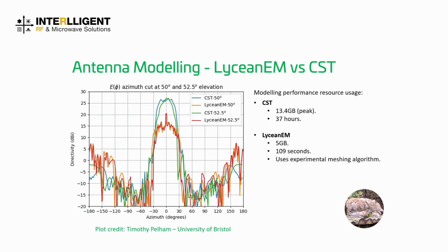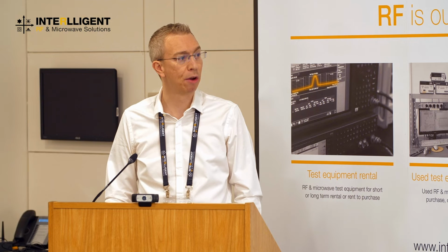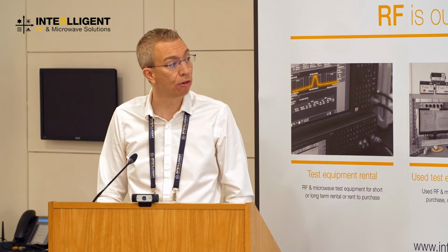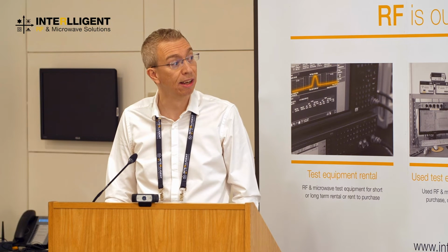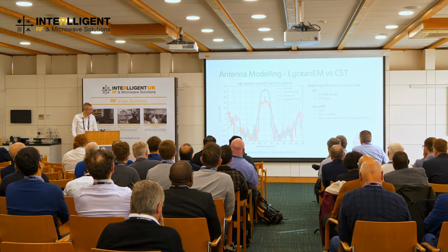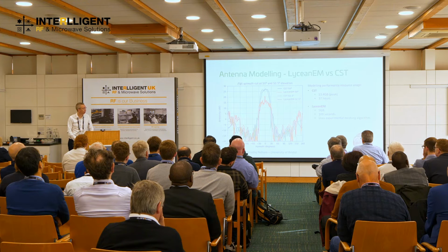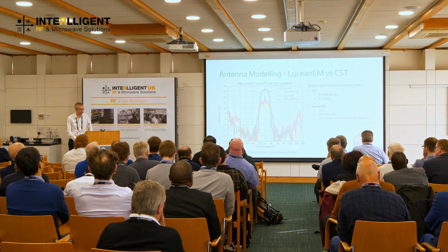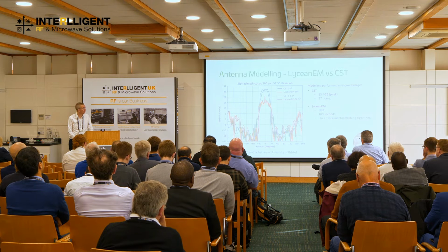Timothy Pelham at the University of Bristol did some modelling for me based on a load of measurements I did on this antenna, because we've got very little information on it. And he's developed a package called Lyceum EM, and this uses a ray tracing technique and an experimental meshing algorithm to do really fast measurements of large volumes of area where you've got arrays of antennas. And he was able to crunch the numbers quite quickly when compared to CST, hundreds of seconds versus many hours. There is a link in the presentation to get more information on this, but for those doing antenna modeling on platforms, it may well be an interesting solution. It's free, it's open source, Python.